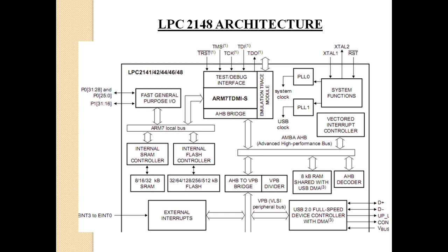So how will you connect a clock? How will you generate a clock in your digital lab? You will be using something known as trainer kit. Inside that, how will you make the clock? Clock means the clock signal, you know, no? How will you develop that clock? By using something known as 555 astable multivibrator, right? But the problem with that is that you will not be able to produce an accurate clock. Say in the case of your laptop, you are telling that say 3.2 gigahertz. 3.2 gigahertz means always the processor should be getting 3.2. If there are some variations in the clock, the working will be affected. So the 555 astable multivibrator problem is that it is not accurate.